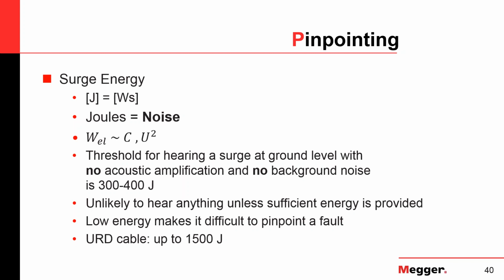Because if you, let's say, have a thumper that can go up to 16 kV and 16 kV only, there's no lower stage, you will only get your maximum energy at that voltage. Now, because the energy goes with the square of the voltage and not just with the voltage, if you thump at 8 kV instead of the full 16, the energy will be a quarter. Not half, it will be a quarter. That means the lower you go, the less chances you have to create noise. And this is the reason for the introduction of multi-stage thumpers, which are standard today.